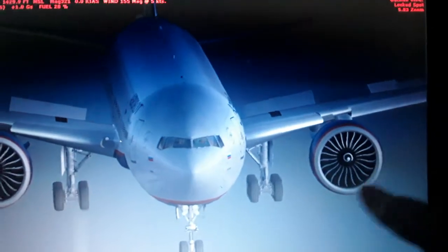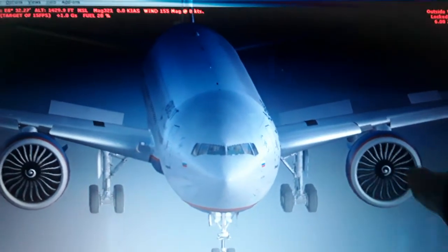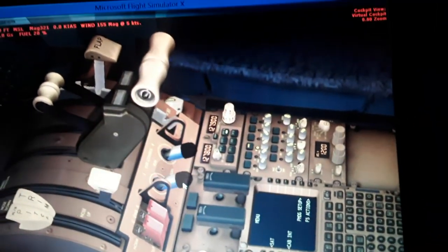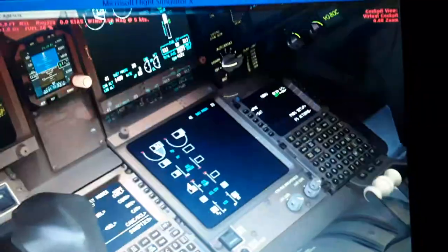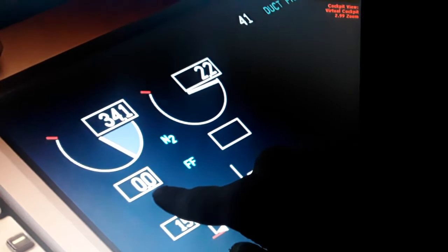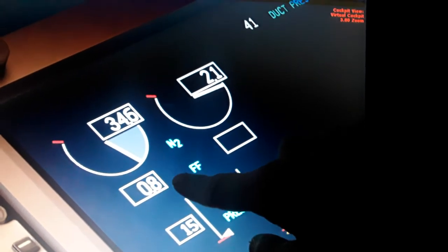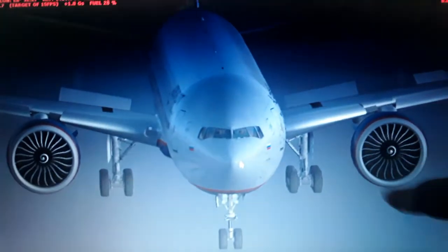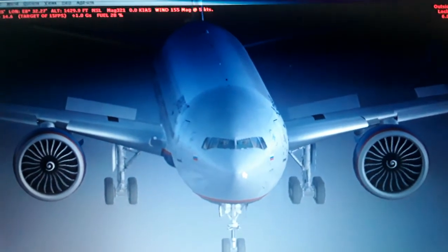You will see here the engine start compressor is spinning the left wing engine faster and faster, so we can admit the fuel now. You can start the fuel flow, so you can start the left wing engine like that. You will see the N2, and the fuel flow is 0, it will become higher, above 0.1, 1000 kilograms right now. So this makes the engine spin faster now.